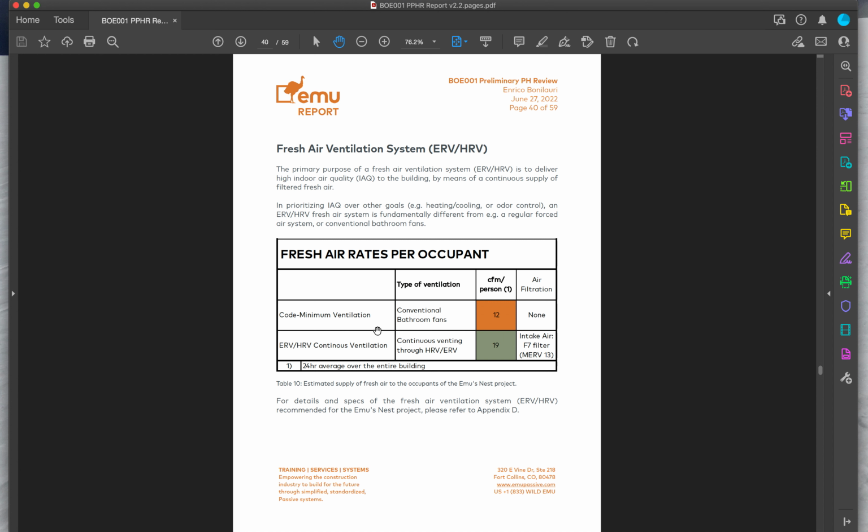And keep in mind that this kind of ventilation has no filtration. So any pollution that is present on the outside would come in. In my case, it's so dry, it can be very dusty outside. And when it is pollen season, both the aspen and the pine release a lot of pollen. So if you're allergic, that can be hell. If you're in the city, you can get a lot of pollution coming in, or if there is a lot of wildfire smoke outside, or whatever type of pollution, you have no way to filter it out before that pollution comes in.